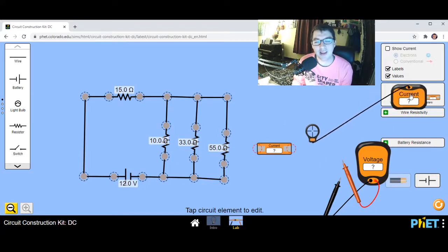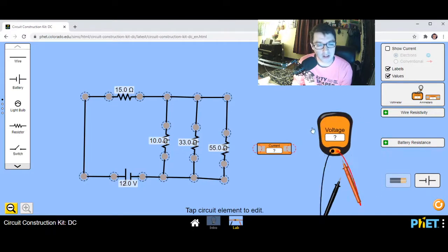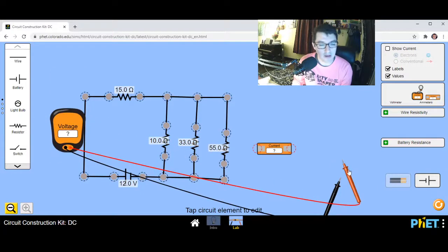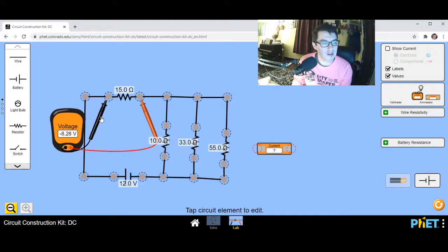But the lab exam wants to test your lab skills, and one of those things was how we connect an ammeter to measure current. The reminder I'm going to give you is that the ammeter must be installed in series. The voltmeter, when I'm wiggling around on the screen now, is in parallel. So all I need to do is touch my 2 leads, right? Just like we had in lab, I don't need to change anything about my circuit when I measure the voltage with the voltmeter.